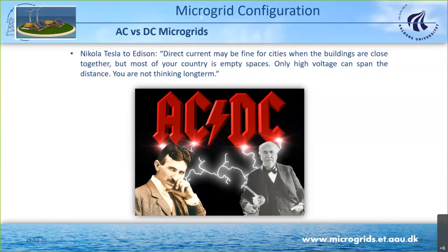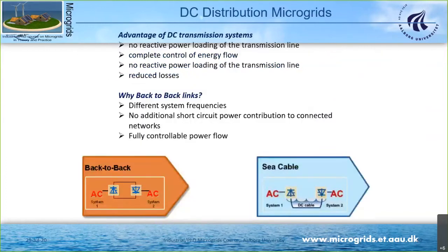And we can see that the same dilemma is happening when we talk about offshore wind. When we talk about offshore wind, of course, with long distances, several hundred kilometers, there is a crossing point in which AC doesn't make sense anymore, and DC starts to pay off. But of course, you need a certain distance. You can see that when we talk about offshore connections, it's like extending a back-to-back converter, so basically splitting it and making a huge DC link.